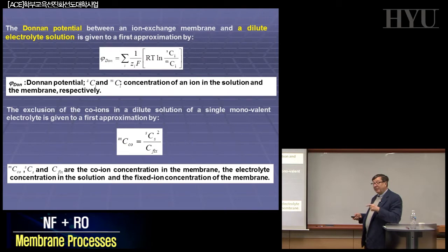But to have a membrane active in terms of high selectivity at this high concentration, you need a very high charge density. Otherwise, there is no exclusion. The system will not work as a selective membrane, so you cannot create reverse electrodialysis. So today you have to produce new membranes with very high charge density. And that is an interesting area, as I was mentioning already.